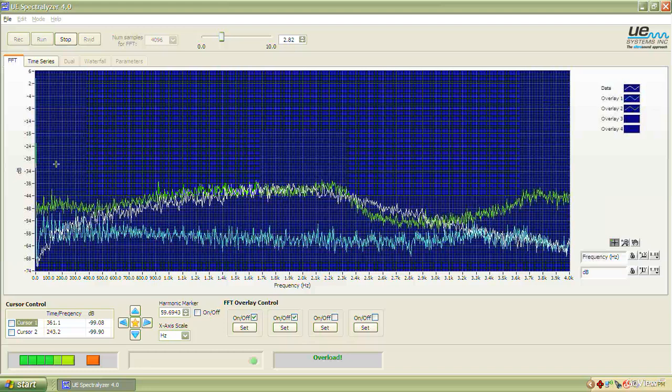We're looking at time versus amplitude or decibel, and we're looking at the events occurring. We don't have any overlays, remember that, and the one thing we do have is cursor 1 and cursor 2. Now the nice thing about cursor 1 is it's going to calculate my frequency for whatever I'm highlighted on. So let's turn cursor 1 on. It's nowhere on the screen really, so let's hit the star button, bring it to center, and then I can grab that, and notice that it's going to calculate my frequency for me right here, which is 0.00198027 hertz. So a very low frequency on that, right?